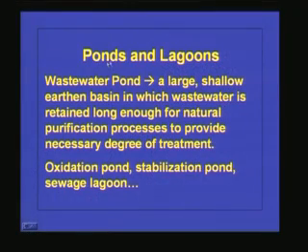We are allowing the waste to be treated by natural forces. Whatever is happening in nature, we allow it to take place in a proper manner, and the waste treatment will take place. That is what is happening in ponds and lagoons. So, what is a wastewater pond? It is a large, shallow earthen basin in which wastewater is retained long enough for natural purification processes to provide